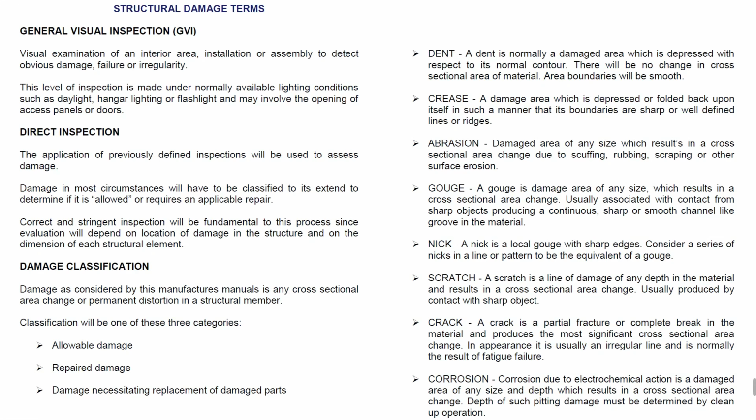Because typical during line maintenance are the dents. Dents are something really typical. So yes, dents, okay, I can assess dents. I'm professional, yes, but there is one story if the dent is on the leading edge. It's another story if the dent is on the inlet cowl of the engine.